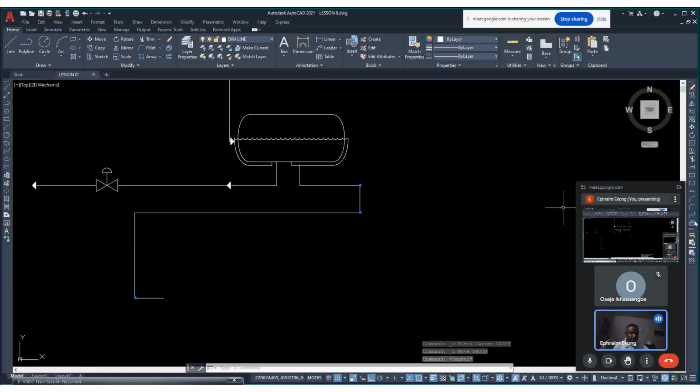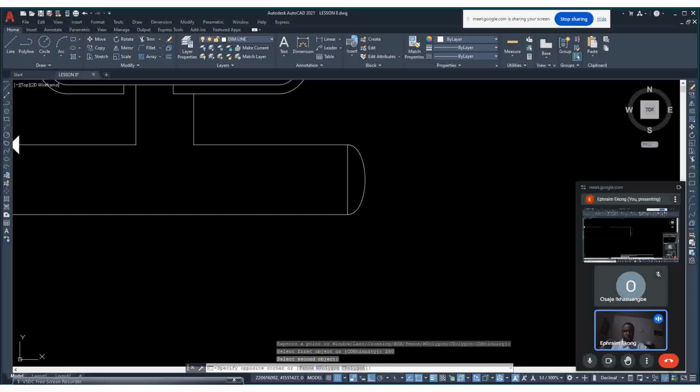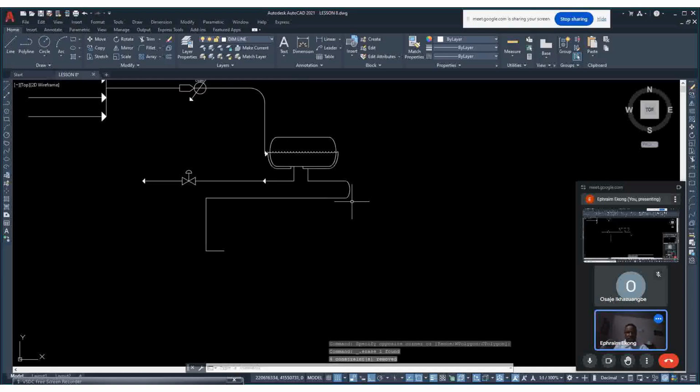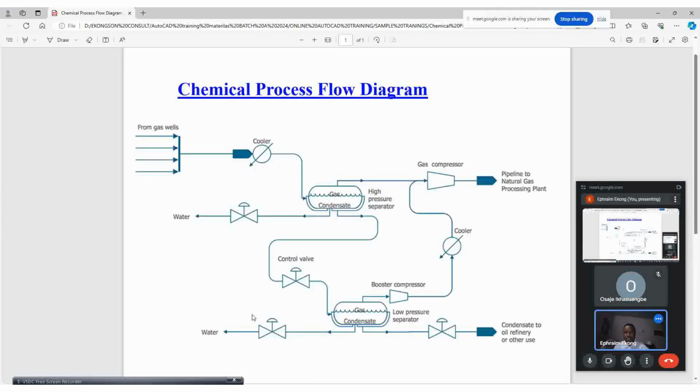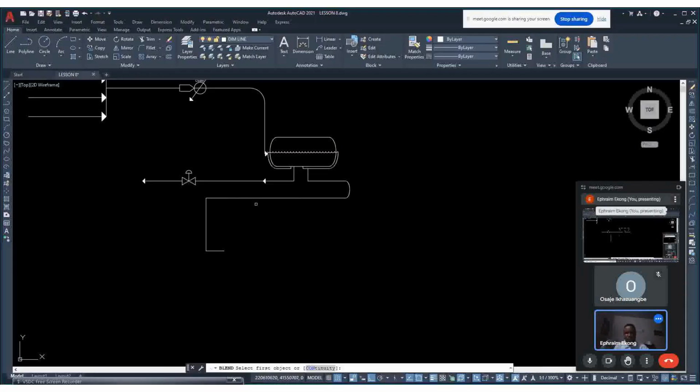Click on fillet. You type R, enter, you type 250 for the fillet radius. Enter. Click on this line. So you see, it has achieved this, okay? So I was trying to expand this line. So that's where the difficulties came about. Okay, so what next? We want to achieve this, okay? So you go to fillet, you click at this point, you click at this point.